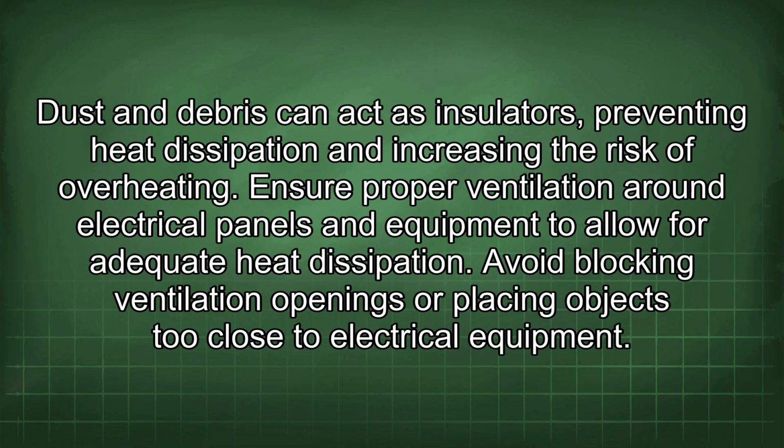Dust and debris can act as insulators, preventing heat dissipation and increasing the risk of overheating. Ensure proper ventilation around electrical panels and equipment to allow for adequate heat dissipation. Avoid blocking ventilation openings or placing objects too close to electrical equipment.